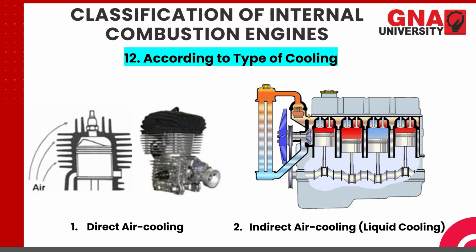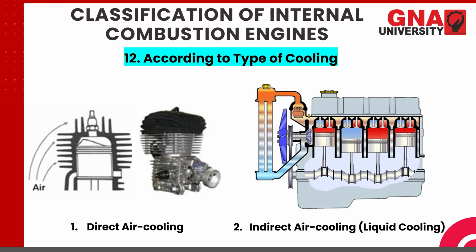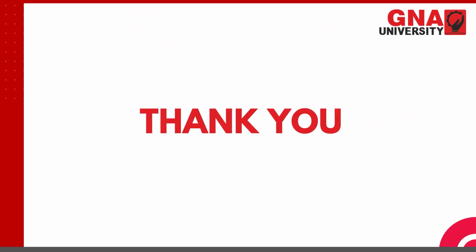So these are the 4 cylinders wherein the coolant moves around the water jacket provided around the cylinders. You can also see the thermostat valve, which decides when the valve going into the radiator will open. When the coolant reaches a particular higher temperature, at that point it will be sent into the radiator and the radiator will remove its heat. So that is the end of this classification for now.